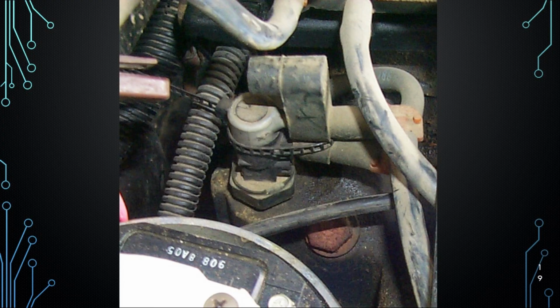These were crazy to diagnose. Say you had an engine with EGR that would start to knock and then the knock would go away. That would be a thermal vacuum switch that was coming on too late, giving you EGR valve operation way beyond the point where the engine had already warmed up and needed the EGR. That was the era that we dealt with it.